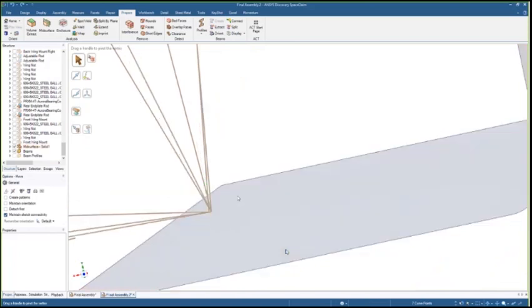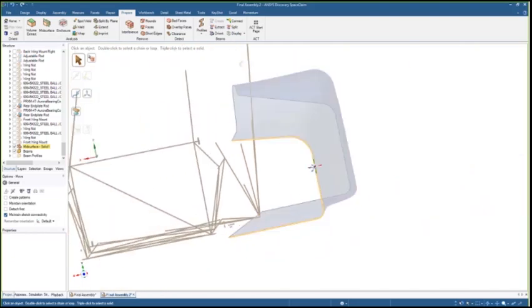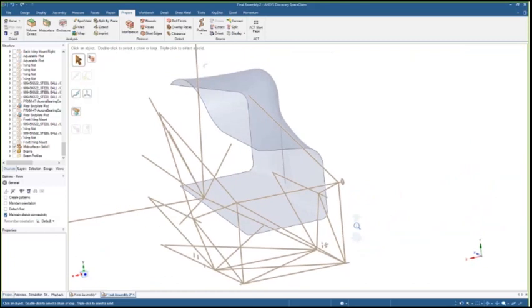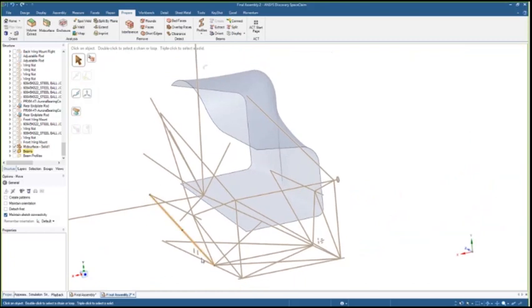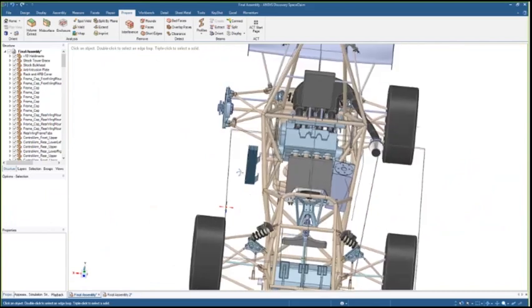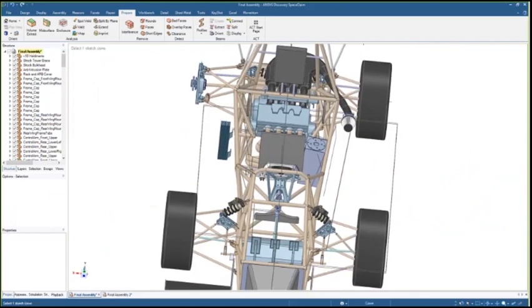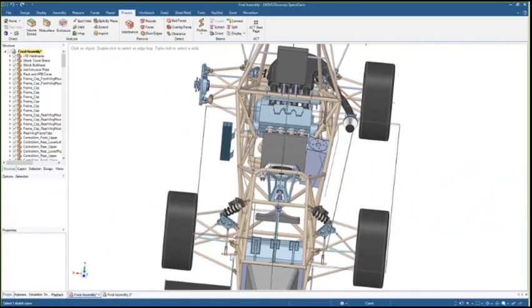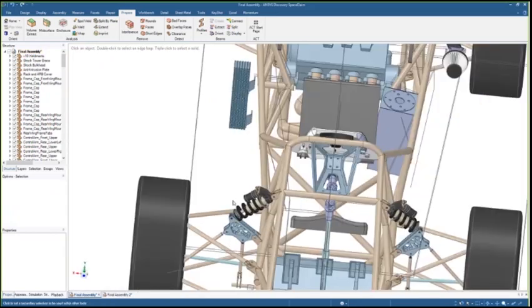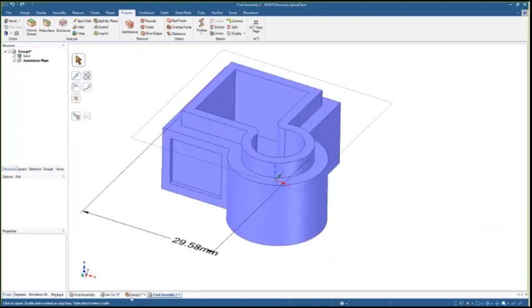There, drive it to 0 like that. Not sure why the up to didn't snap correctly, but these are the types of geometry preparation that SpaceClaim offers. The whole idea of preparing a model with SpaceClaim for simulation or meshing is to remove detail, whether that's simplifying from solids to beams and shells, removing detail like holes and rounds, or being able to set up parametric studies on these models.